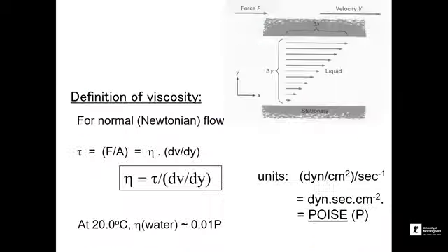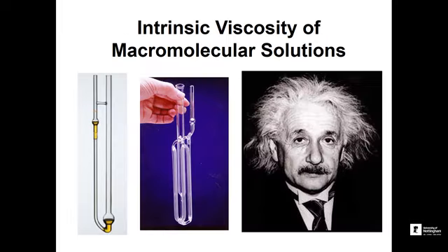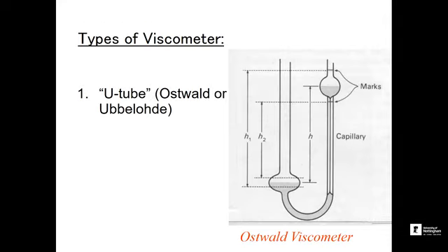And this one here is the same as a U-tube. It's just got the capillary bent round several times, because by having a very, very long capillary, you can increase the resolution of the measurements that you're making.